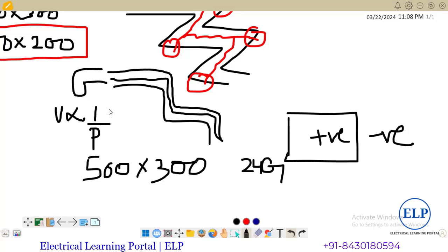Another thing, sir: in our project, they are using three things, rectangular duct, round, and elliptical. In the ceiling area, they are using rectangular, and they are using insulation also. In open areas without ceiling, they mostly prefer rectangular and circular. Another thing is that for rectangular they are using insulation, but for circular and elliptical they are not using insulation. That is the cost-effective solution actually.